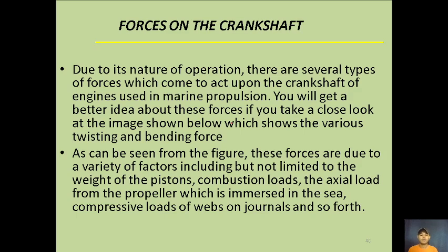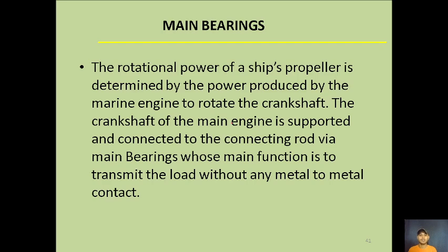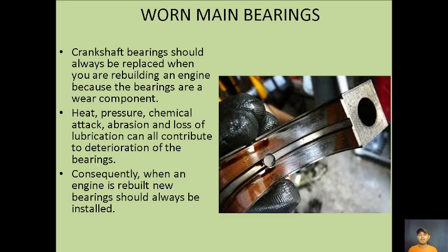These forces are due to a variety of factors, including but not limited to the weight of the pistons, combustion loads, the axial loads from the propeller immersed in the sea, and compressive loads on webs or journals, and many more. The rotational power of a ship's propeller is determined by the power produced by the marine engine to rotate the crankshaft. The crankshaft of the main engine is supported and connected to the connecting rod via main bearings, whose main function is to transmit the load without any metal-to-metal contact.